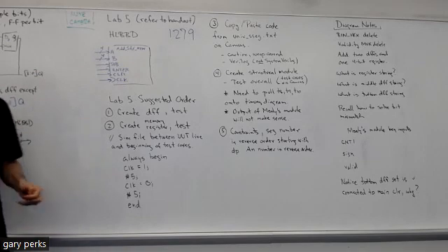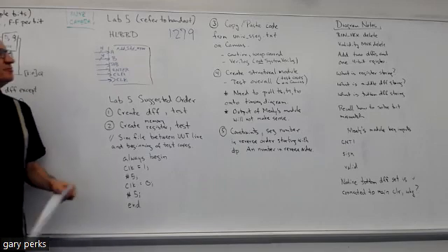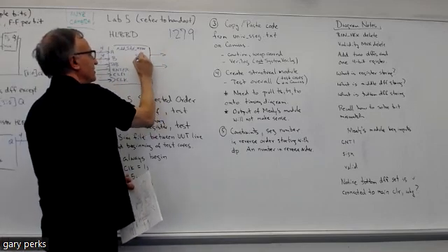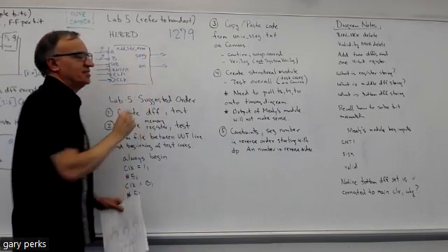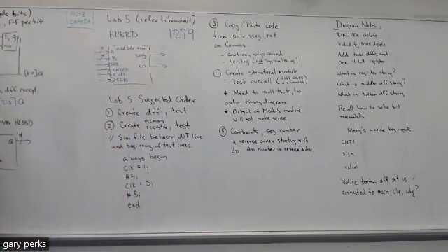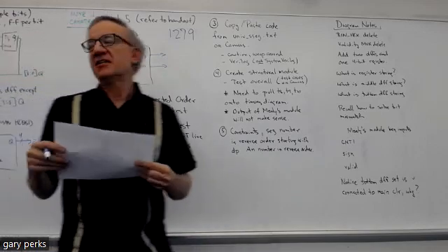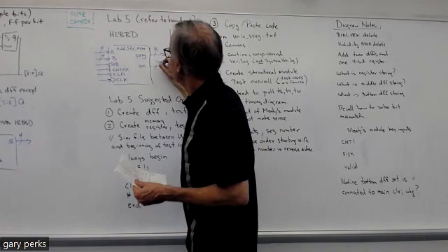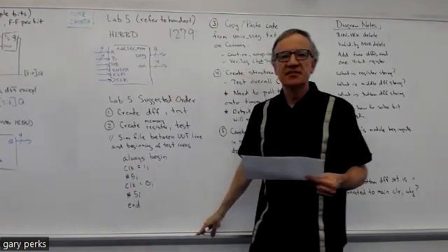All right, but how about the main outputs? What main outputs do we have for Lab 5? Looking at the diagram here. The seg and anode. Yep, seg and anode, just like Lab 4, except there is one difference. Do you see what's different about the outputs for Lab 5 compared to Lab 4? Remember, seg was 7 bits in Lab 4. Here, it's 8 bits. An is still 4 bits, right?